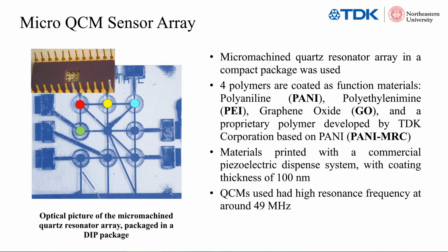The resonator used a high resonance frequency of 49 MHz. They were coated with 4 different functional materials. The materials were printed with a commercial piezoelectric dispense system with a coating thickness of 100 nanometers.